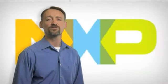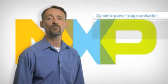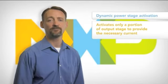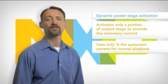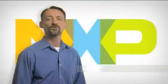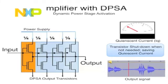Both of these products feature dynamic power stage activation. This is a system where only the portion of the output stage that is required to produce the needed current is turned on. So in most applications, it will use only 1/4 the quiescent current of a typical Class D amplifier. We'll start audio playback with a moderate level signal. This would be something along the lines of what you would normally be listening to. As you can see, only the portion of the device that is needed is on. The rest is shut down, saving power.